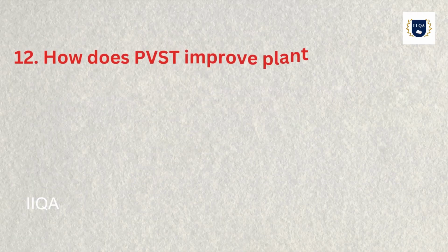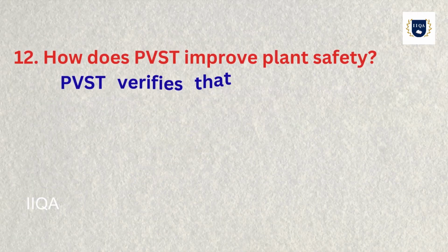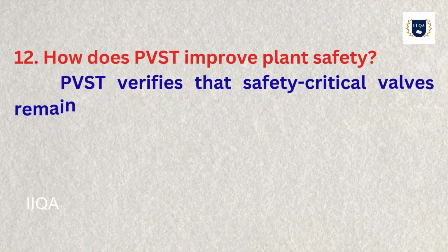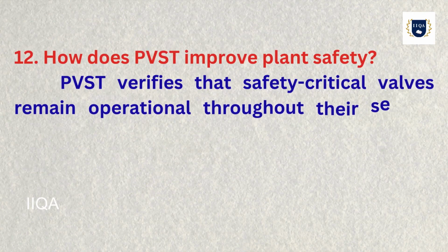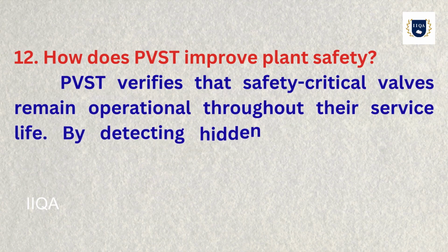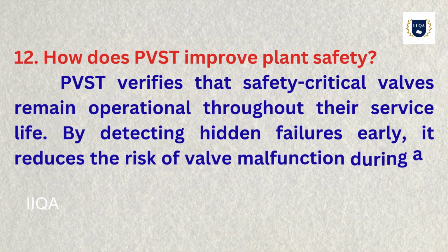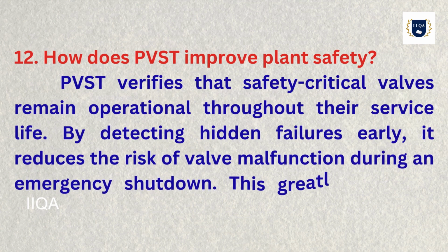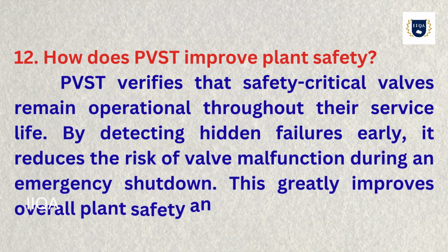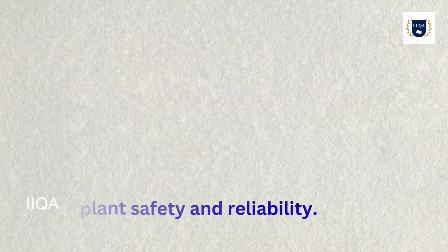12. How does PVST improve plant safety? PVST verifies that safety-critical valves remain operational throughout their service life. By detecting hidden failures early, it reduces the risk of valve malfunction during an emergency shutdown. This greatly improves overall plant safety and reliability.